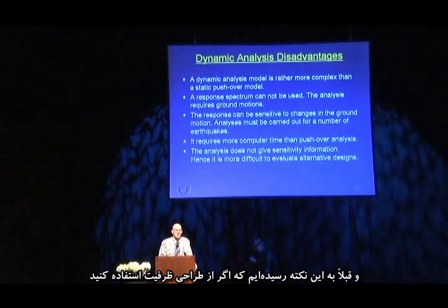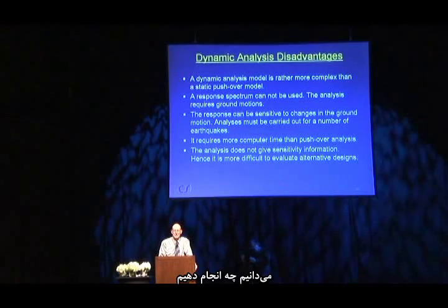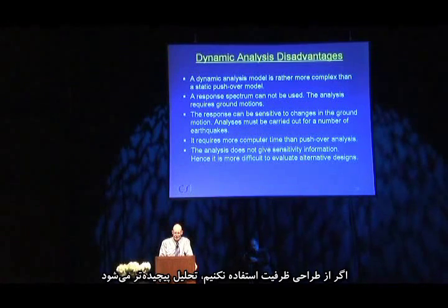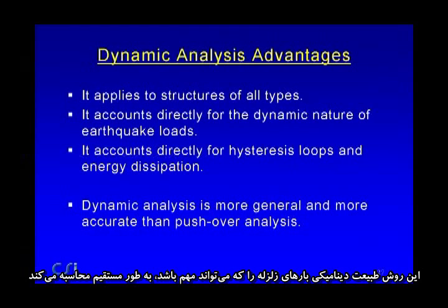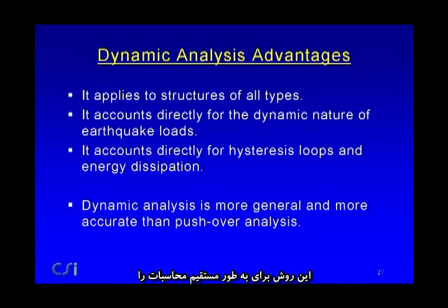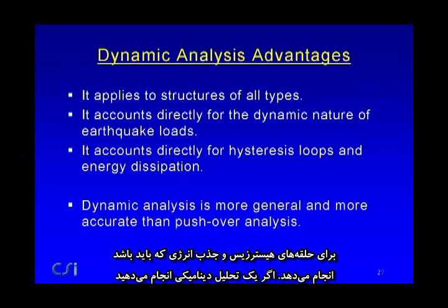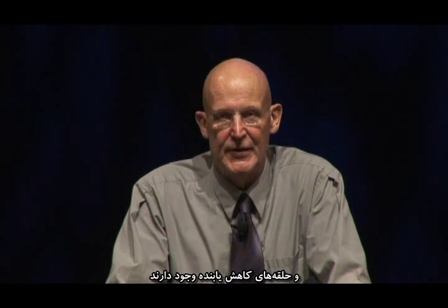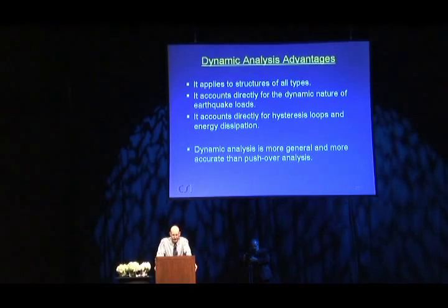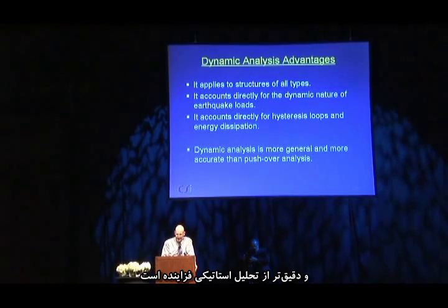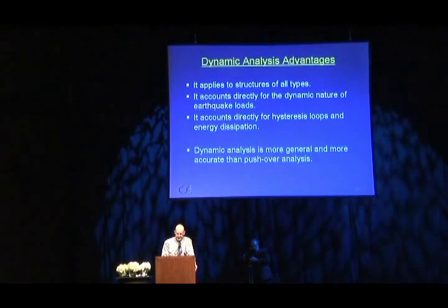And we've been through this before. If you use capacity design, it's a lot easier to decide what to do. If you haven't used capacity design, it's a lot more difficult. The advantages: it applies to structures of all types. It accounts directly for the dynamic nature of earthquake loads, which can be important. It accounts directly for hysteresis loops and energy dissipation, or it should. If you run a dynamic analysis and there are degrading loops, your model should reflect that. So it's more general and it's more accurate than pushover analysis.